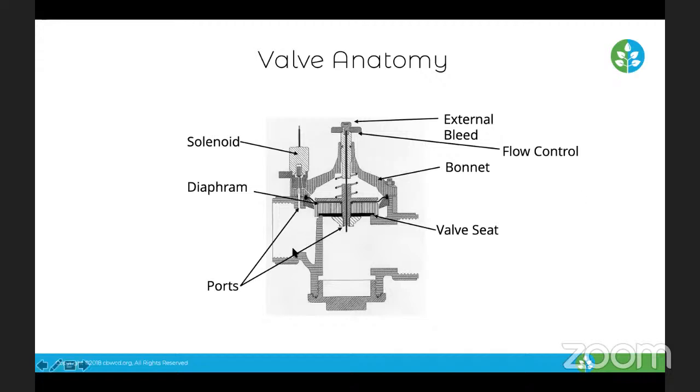We opened up the valve and it was a huge cap from one of the pipes. The city was doing a repair and one of their galvanized pipes comes with a cap, and somehow that got in the line and was jammed inside the valve. The valve was not closing and the valve was damaged. So things like that do happen, not very often, but checking the valve seat will cover that.